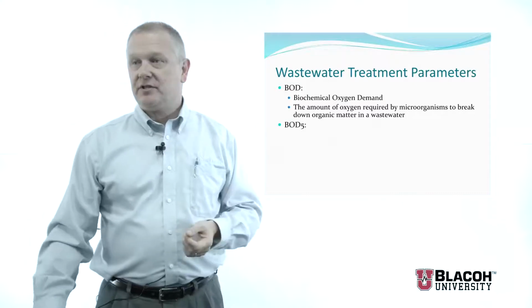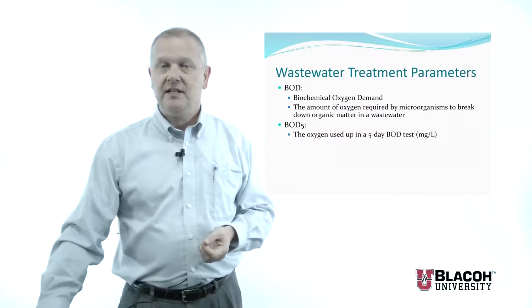The actual test we use is called a BOD5 test. The way the BOD5 test is performed is we take a bottle with water in it that has been aerated, and we measure the oxygen concentration in that water. We add our wastewater sample and a seed of microorganisms that will break down that waste.